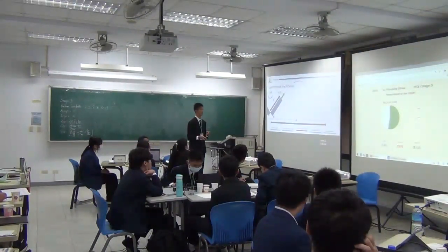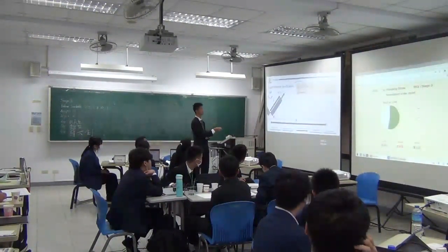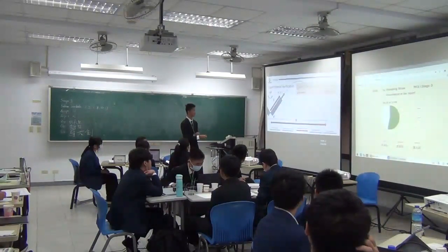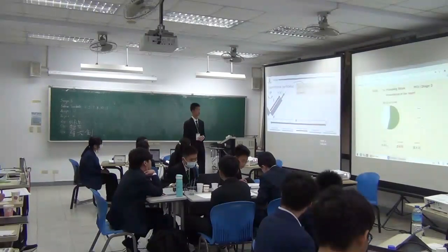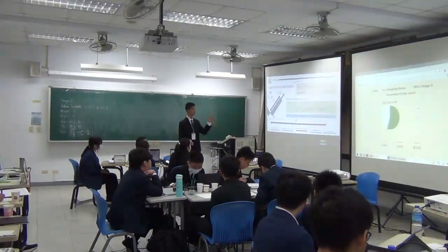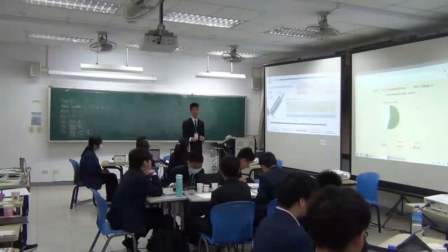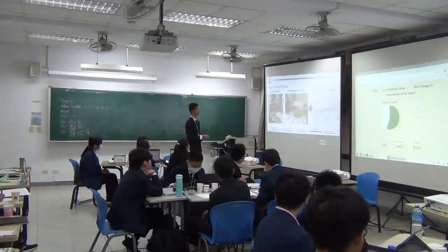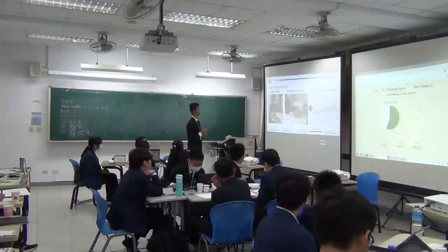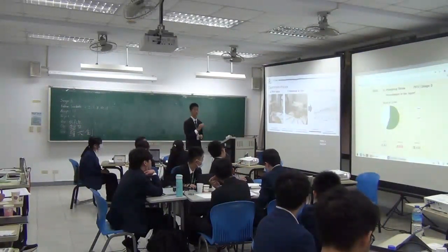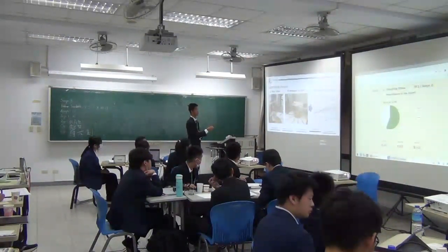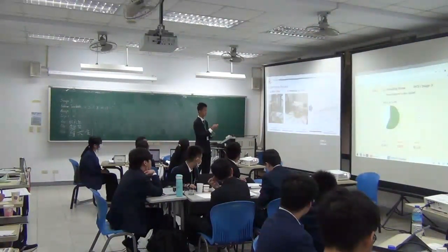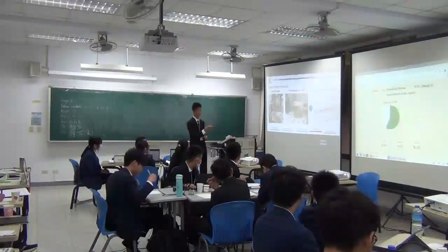So how can we verify the experimental? Well, we can use basic dynamics to find the relationship of the range of scattered water droplets with the exit velocity, which is given by this equation. So if we compare this with our theory, we can see if our theory is correct. So for the experiment, the process is I use a high-speed recording iPhone at 240 FPS to record the angular velocity, and I measured the scatter range with the ruler and then compare with theory.